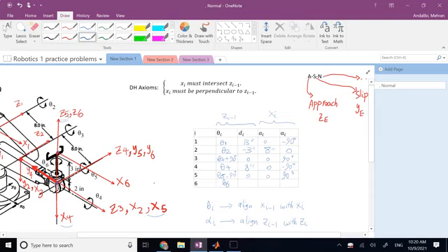How much? So what you need here is 2 inches plus 3 inches, right? Because by 2 inches you go from center of this wrist to the center of the end effector, and then another 3 inches to the center of the grip, so it is going to be 5 inches. And then you don't need any motion along new x. And now what about the z's? The z's are already aligned, so no twist is needed. There we go. So finally, I guess I got my DH table complete.